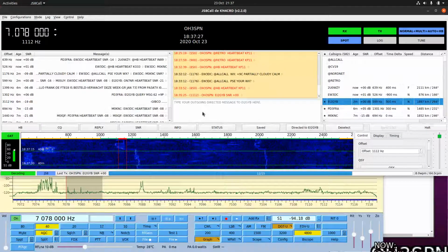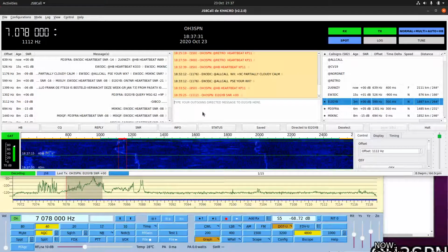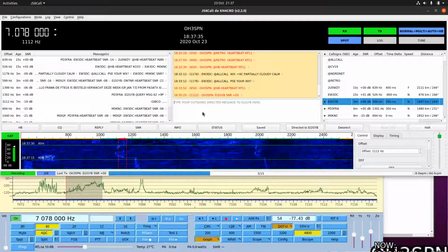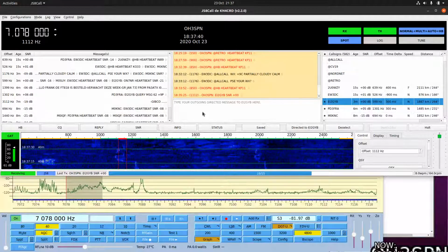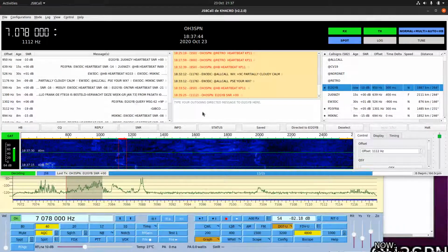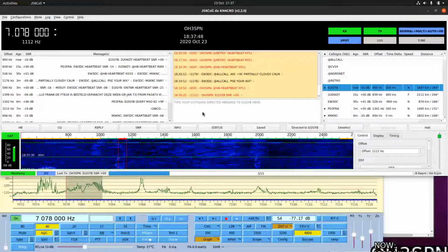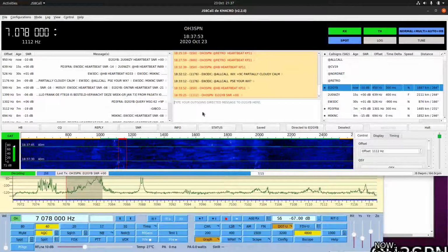And I know that their noise floor is traditionally, on a signal meter, maybe plus 6 S points. So if you're competing against that level of noise, then minus 12 dB, hang on, 6 dB per S point, I'm still about S4. At their end, I'm just swamped by their local noise floor.